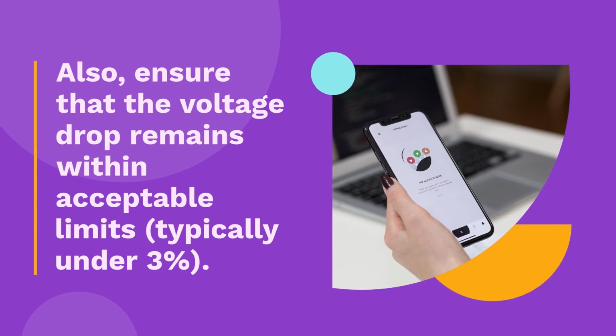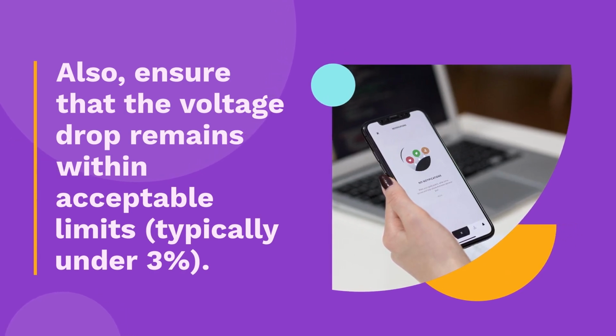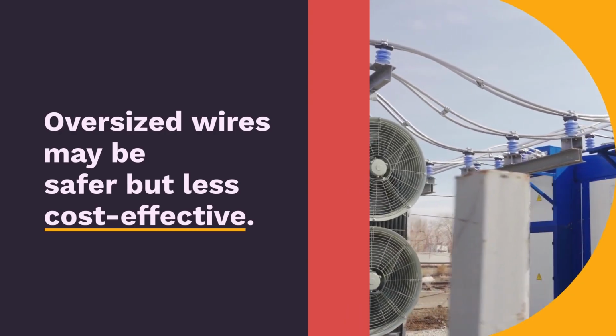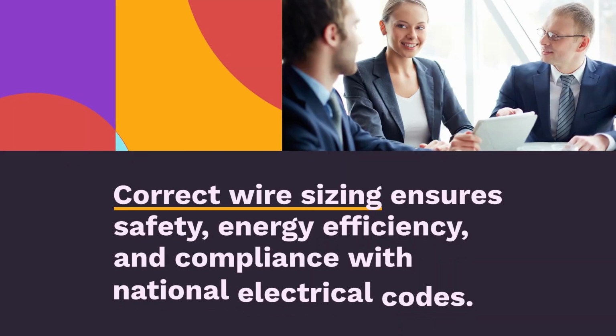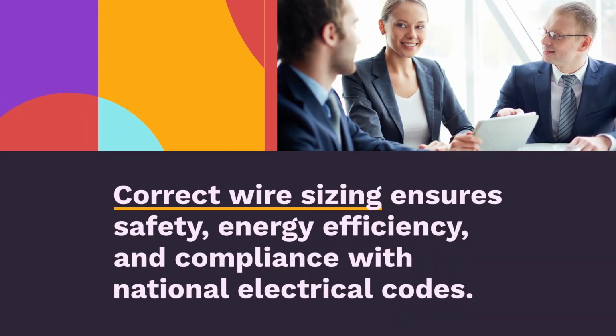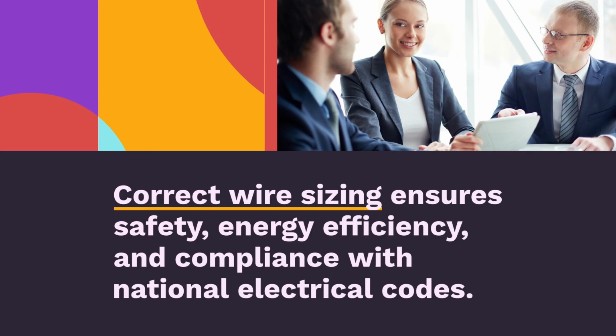Also, ensure that the voltage drop remains within acceptable limits, typically under 3%. Oversized wires may be safer but less cost-effective. Correct wire sizing ensures safety, energy efficiency, and compliance with national electrical codes.